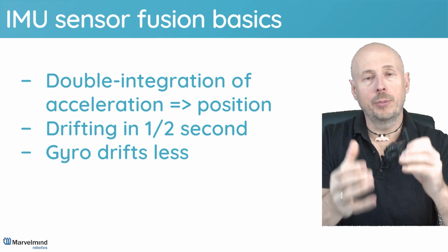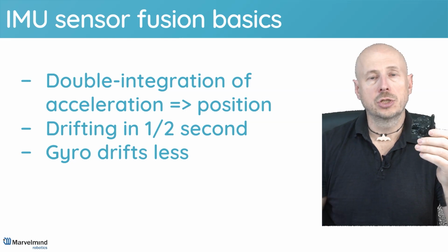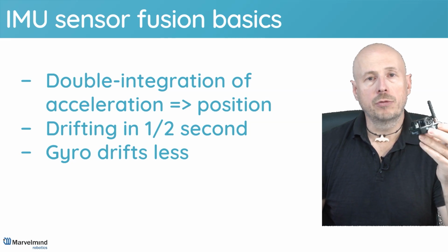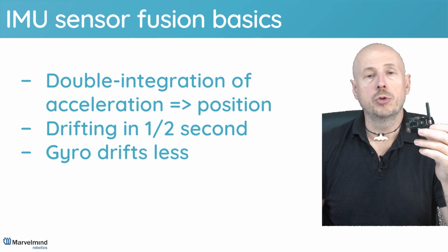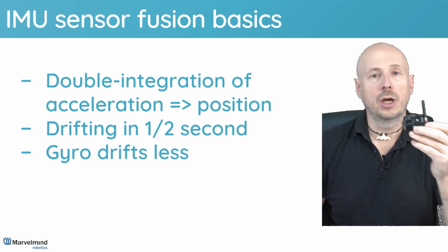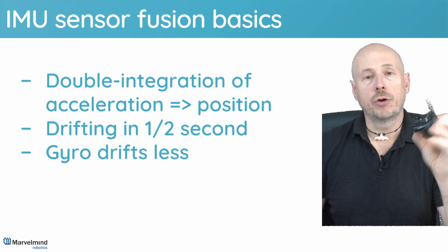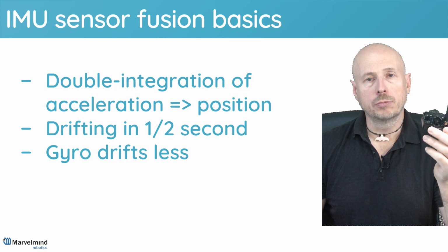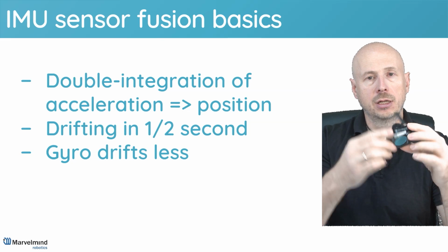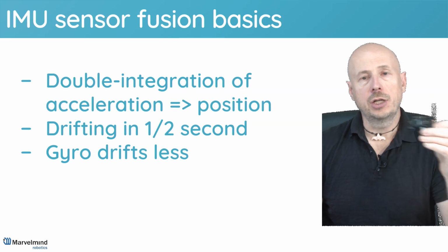And by smartly combining, basically doing the sensor fusion, it's possible, and the result is the sensor fuse data, which is very accurate, because IMU provides no jumps, and IMU provides very quick 100 Hz update rate, and no drift, because the drift was cancelled using ultrasound-based system. Gyro drifts, of course, but gyro is a lesser problem. You need to very, very accurately know the angle in order to subtract their acceleration from the Earth, from your acceleration.